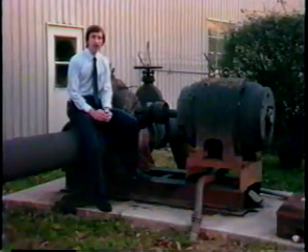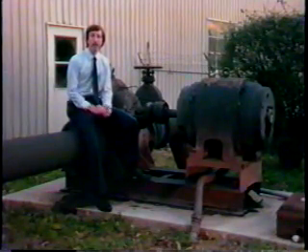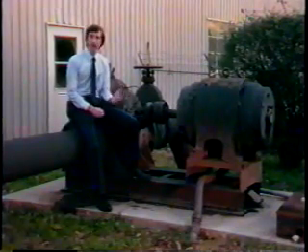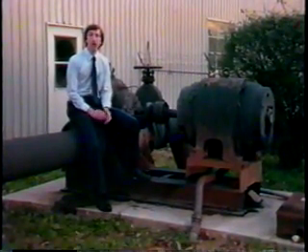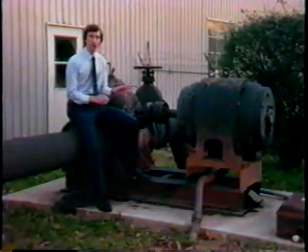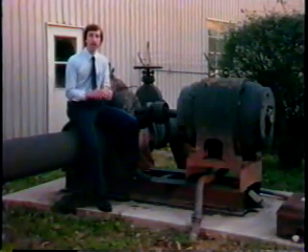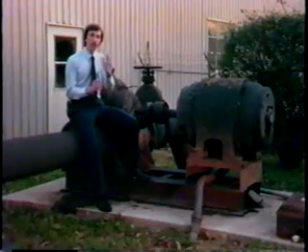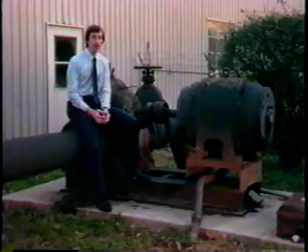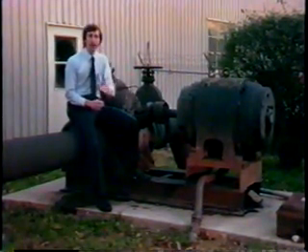What you need to do is know which pumps are running when you're conducting the test. This is very important information and it's very easy to get. Also, you'd like to know what kind of pressure is being put out by the pumps during the test. In particular, you want to be sure that the pump isn't dropping its pressure when you open up the hydrants. For example, if a pump is already pretty far out on its head characteristic curve and you open up a hydrant, what's going to happen is that the pressure at the source will drop.